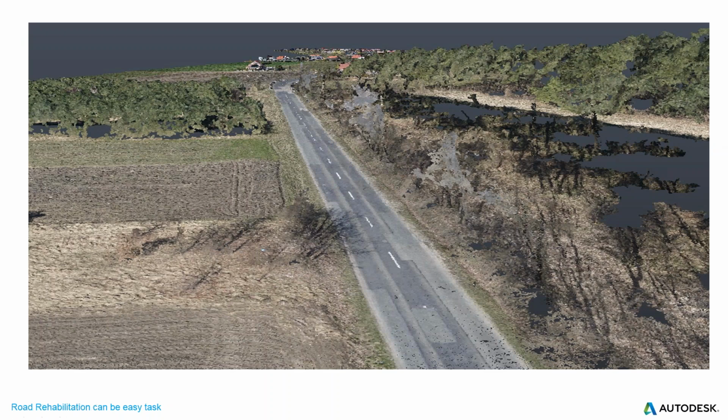So basically, from laser scans, you can create your terrain, and here I will cover what you can do with it. Because I believe that this is also the way it is going: first of all, it's much faster to do a laser scan of the existing road than to do a classical survey, and you will get results very quickly. But obviously, in this case you will have an enormous amount of data, and you should be able to process it. So let's have a look at how we can deal with this, so that you don't have only millions and millions of points, but know what to do with them.